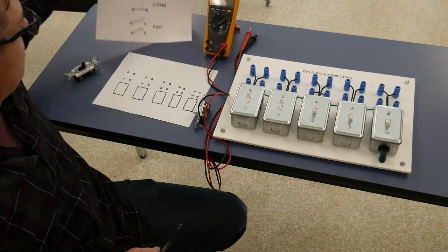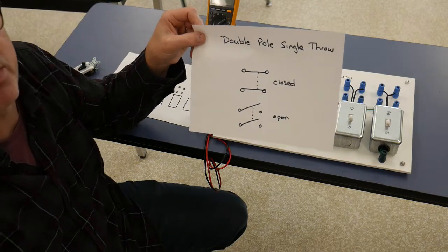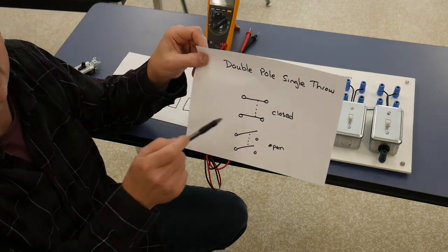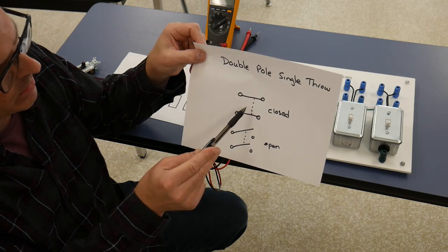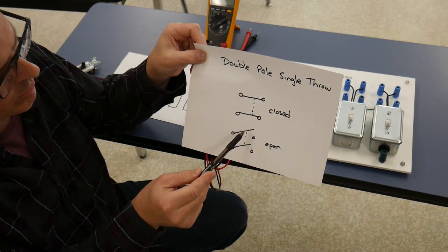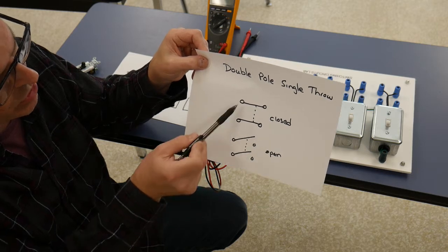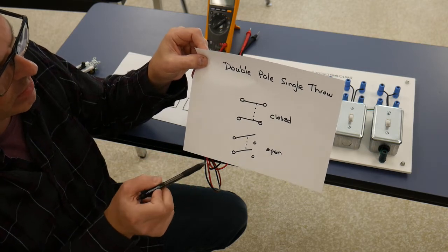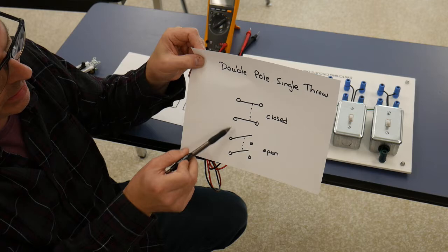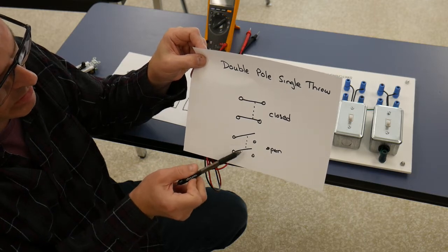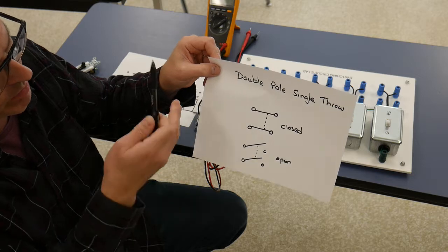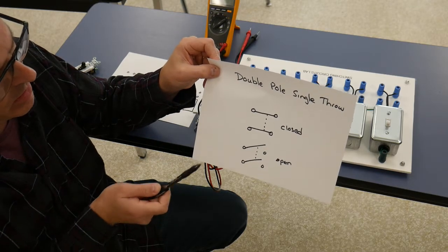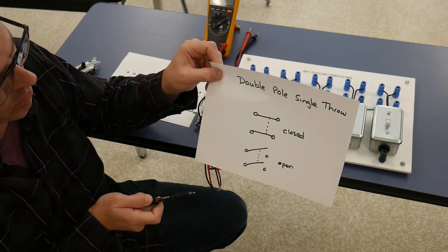Lastly, we have what's called a double pole single throw switch. That double pole single throw, it gives us the option for just disconnecting two line conductors from a load. Okay, it has no mid pivot points. In other words, it can only go in one position. That's why we call it single throw. In other words, we open or close it and that's it. These do not crisscross like the four-way switch.